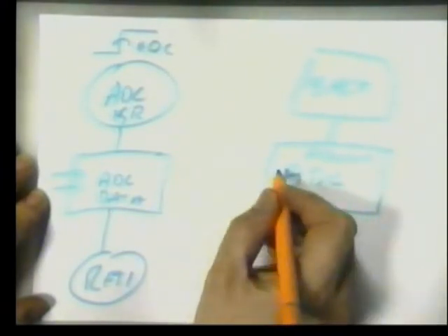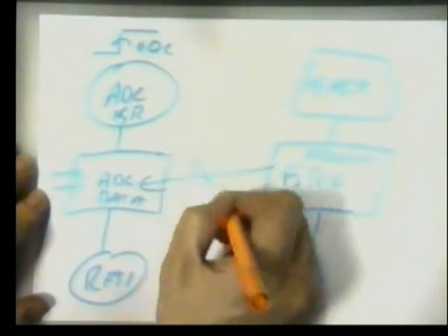This routine is not allowed to access that data. It's illegal for it to do it. Why is it illegal? Because the ADC interrupt could happen anytime it wants. We don't know when it will happen, and it will update the ADC active data areas. We can't come along and just take copies of it whenever we want, because that interrupt could have paused us while we were getting it, in the middle of it, and updated that data.